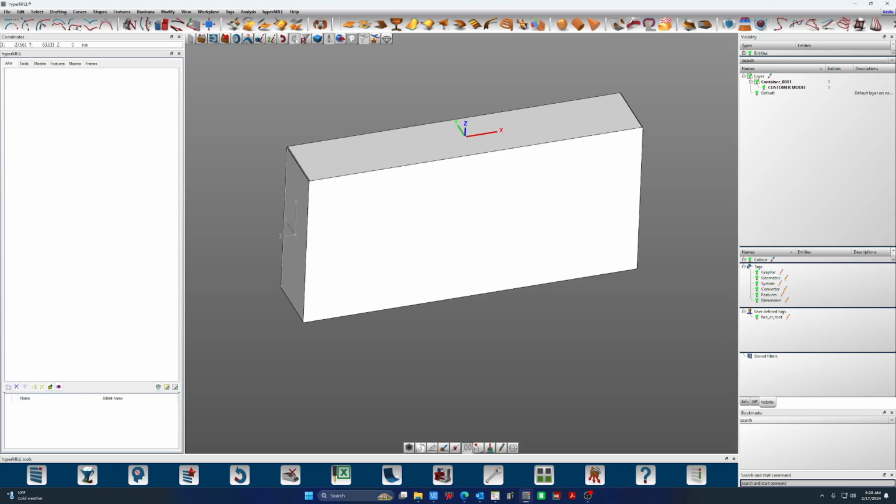Undo, redo. Undo, redo only works in the CAD workspace. In hyperMILL, the way we're going to learn to run is modeless, and your decisions are final. hyperMILL is going to tell you, hey, are you sure you want to do this? As soon as you say yes, there is absolutely no going back.